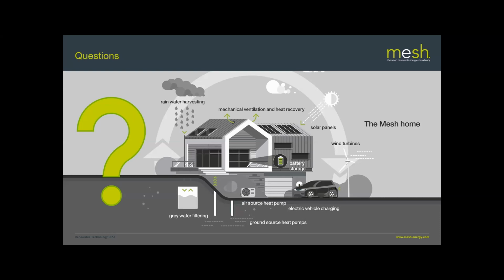So it will provide a proportion of cooling, it will provide a little bit of comfort cooling. It'll take the edge off the temperatures, but it's not the same as an air conditioning system. If your building needs significant amounts of cooling, then you really need to think about an air conditioning system or a reversible heat pump system connected to fan coil units, which gives much the same system.